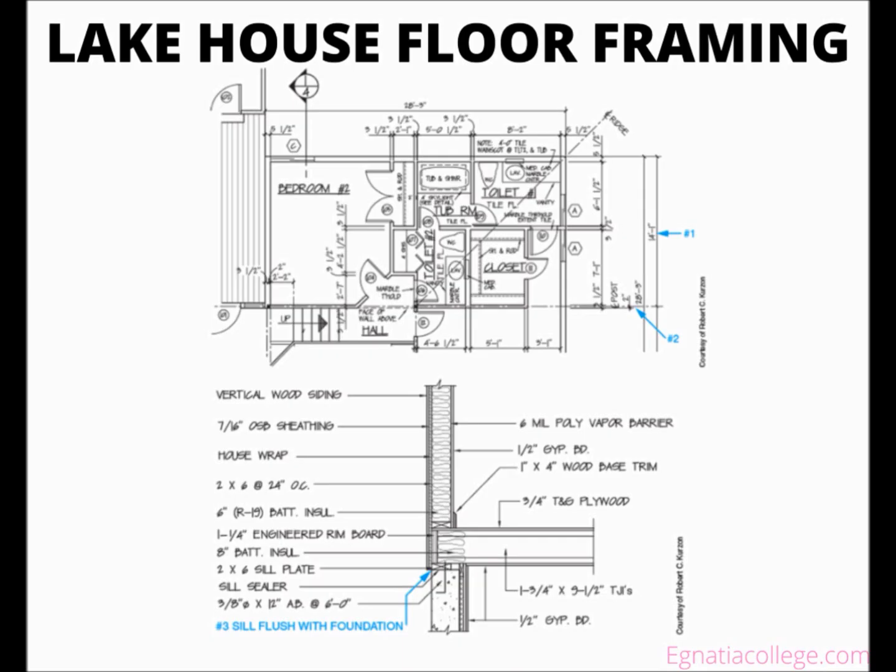The doubled smaller LVLs support the loft. The LVL beams form part of the roof framing. All of the LVL beams rest in beam pockets that are welded to the posts. The structural steel channel, C8x11.5, is bolted directly to the posts.